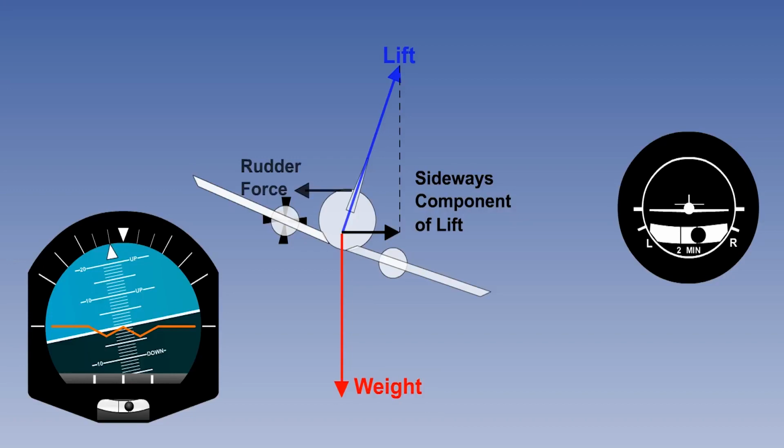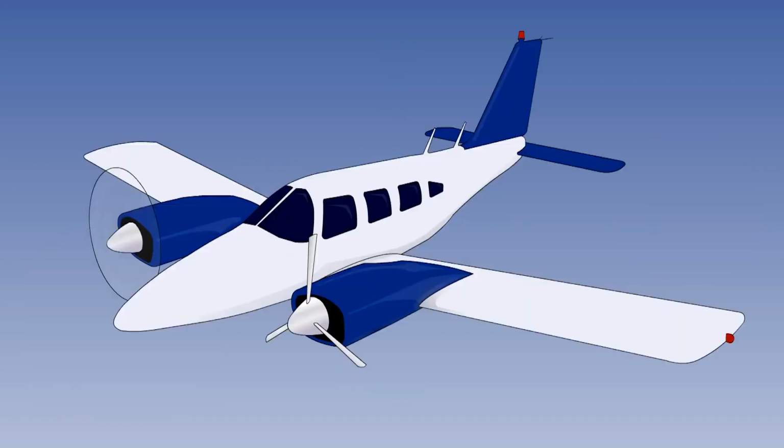The advantage of this method is its better aerodynamic efficiency, without the side slip drag penalty, making it better for use in marginal situations. But it is more difficult than the wings level method for the pilot to fly consistently. In practice, however, pilots will tend to use the wings level method initially, with its simpler handling references, usually combining the techniques only under marginal conditions, when the better aerodynamic efficiency of bank to the live engine or engines is of greater importance.